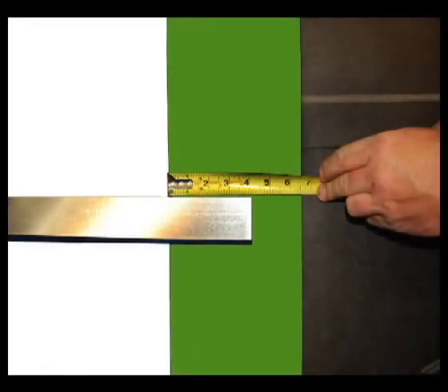After all of the window rough opening waterproofing material or flashings are in place, measure and cut the metal moisture diverter so it extends 4 to 6 inches past each side of the window rough opening. Install the moisture diverter over the top of the window rough opening, making sure there is 1/4 inch per foot slope to drain. Also make sure not to interfere with the flashing or window mounting flange.